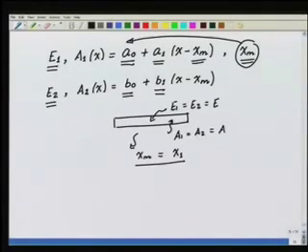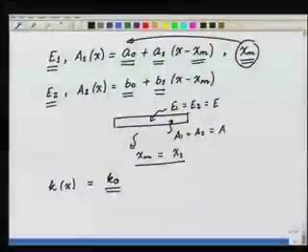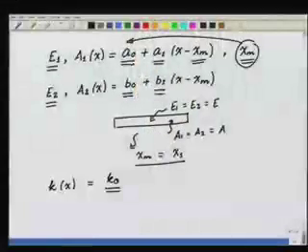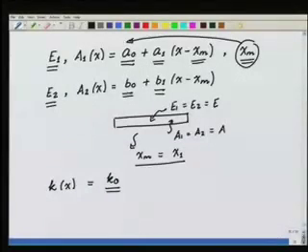Okay. Now, if I have Kx, we know we want it to be a constant, K0. So K0 also has to be inputted as an input data. So as far as material data is concerned, we need to input the point of transition, Xm, we need to input A0, A1, B0, B1, E1 and E2, and K0.